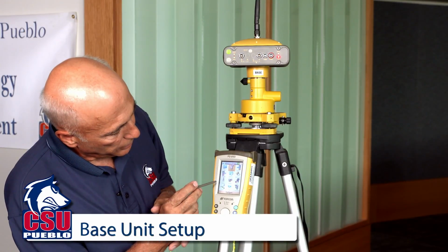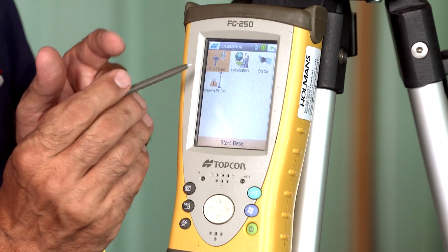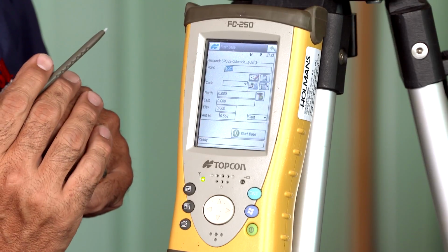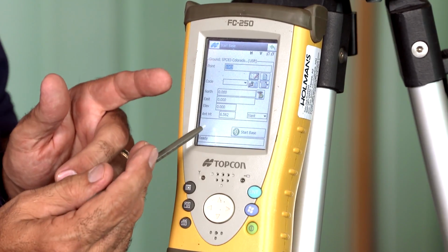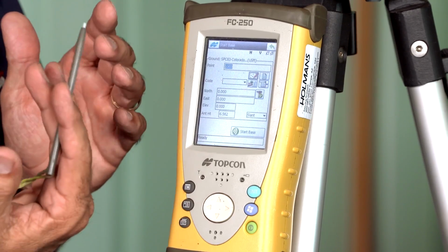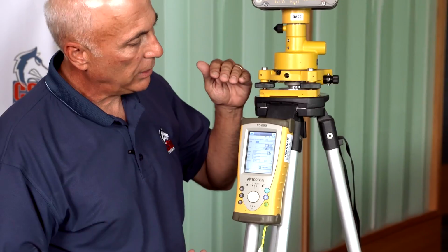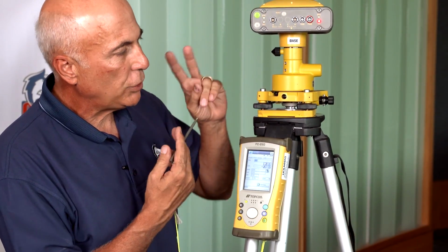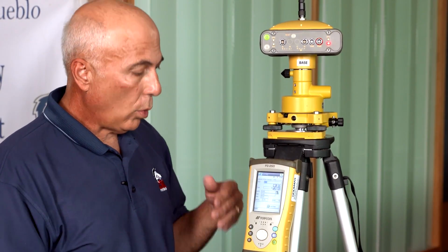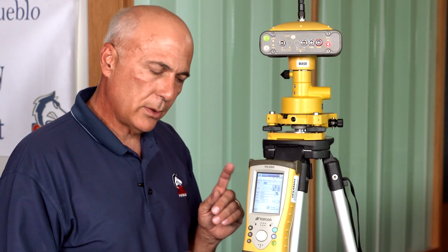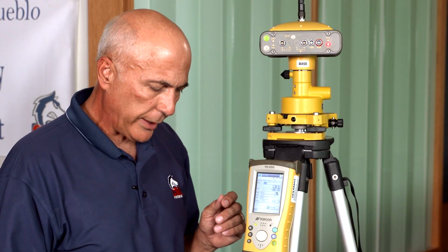So we will go into the initial setup screen. We're going to set up the base unit, and by looking at the base unit, I come up with a series of screens. Now, one of the things that would normally happen, and in our environment today I'm not going to be able to demonstrate this, is that we would have two options. We could either know the location of the point we're setting up over, or we could not know the location and ask the GPS system to find it for us. Either system is usable and very common in today's practice.